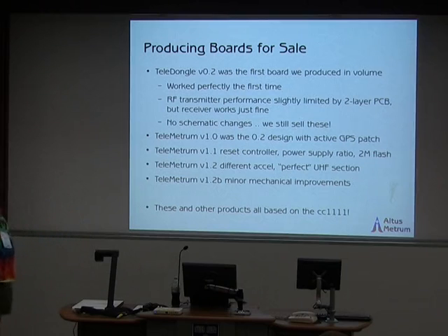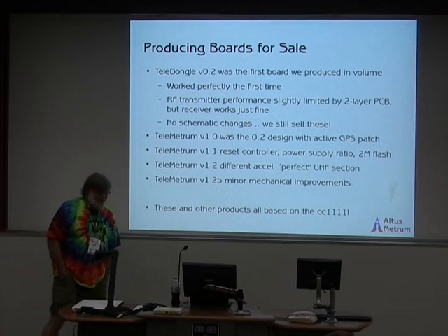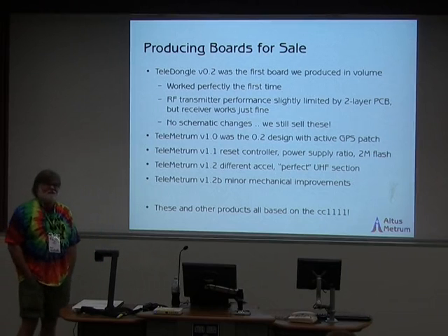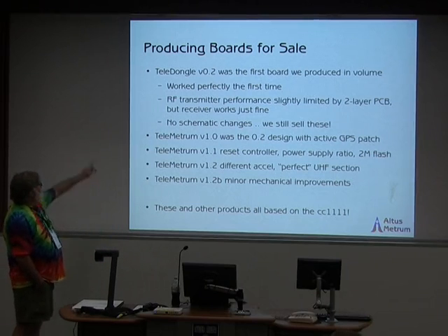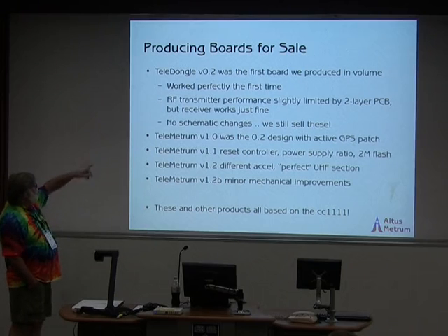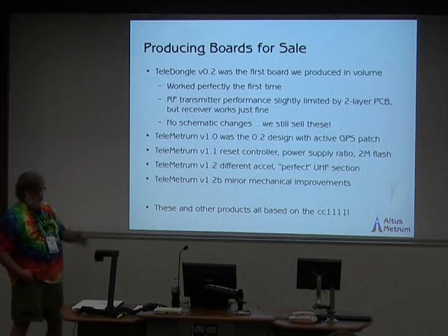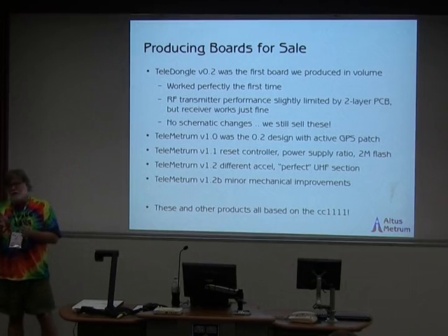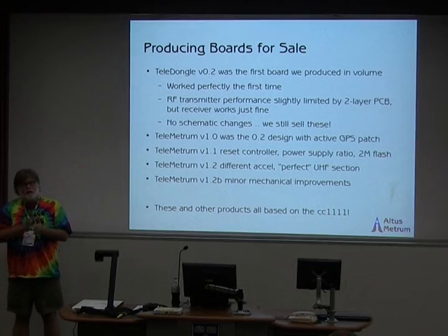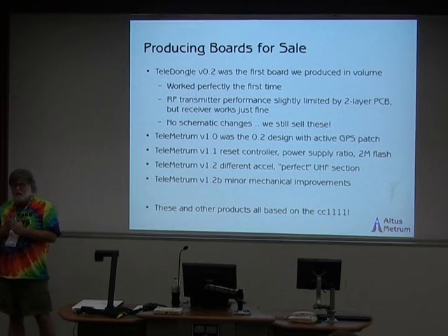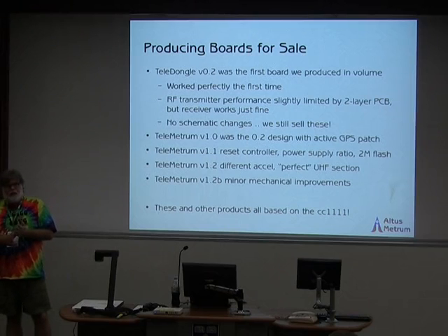It's such a wonderful unit in so many ways, particularly when you're dealing with centimils and gEDA. But the issue is that you cannot achieve a 50 ohm impedance trace on a board that thick with a ground plane on the back side of the board without making the trace crazy fat.